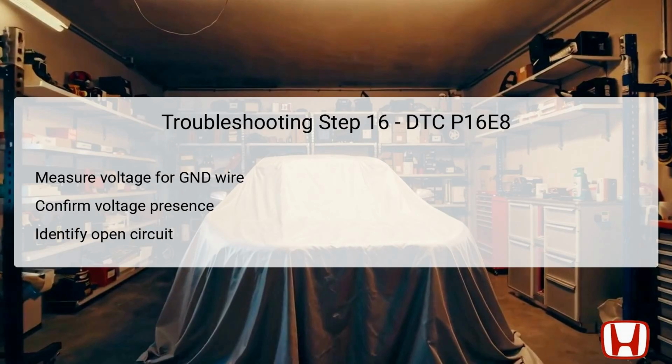In Step 16, there is a clear focus on checking for battery voltage presence between the specified test points for testing ground wires. With the shutter grille connected, establishing the presence of voltage at test points is pivotal in identifying the state of the ground wire between the shutter grille and body.